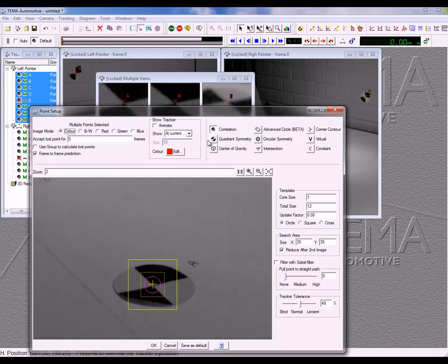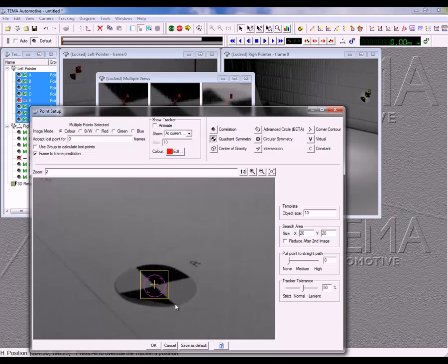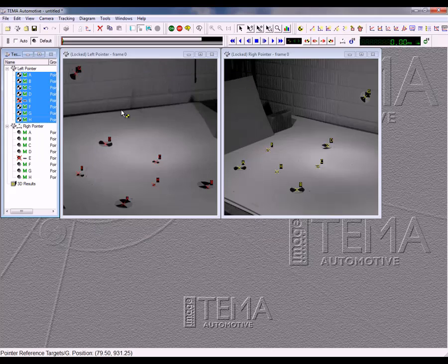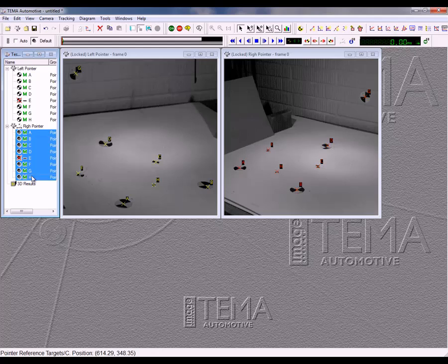If you are using quadrant targets, right-click to set them all to quadrant algorithms, at which time they will click onto the quadrant center lines if they're not right on. If they click anywhere else, you may need to hold down the Alt key to move them.